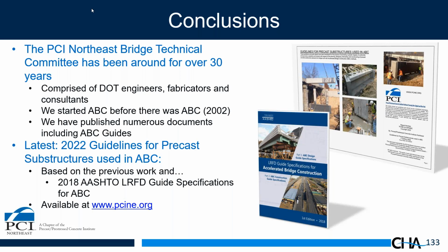Okay. Next question, how would you repair or retrofit the precast connections, say after a seismic event? Yeah, there has been quite a bit of research on retrofit of connections. Caltrans has done a ton of research on post-earthquake retrofits. Essentially, these connections function the same as a reinforced concrete connection. Even with the grouted couplers, at the end of the earthquake, you'd have the crushing of the concrete you'd normally get in a plastic hinge zone.